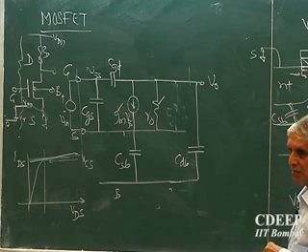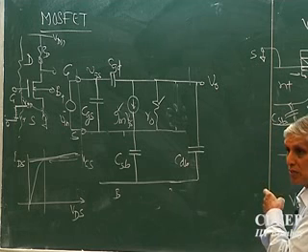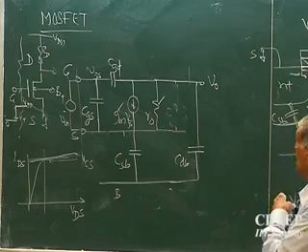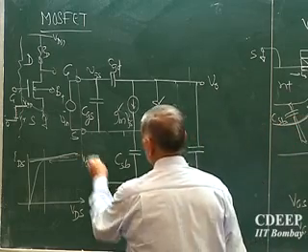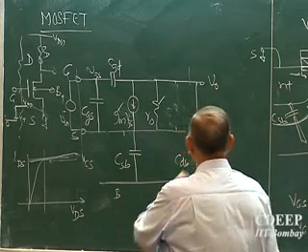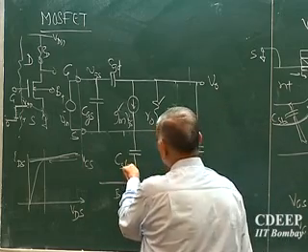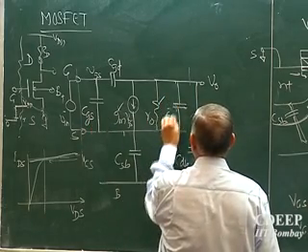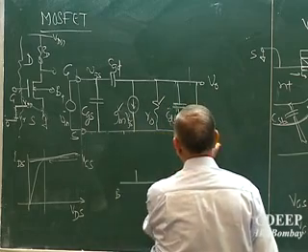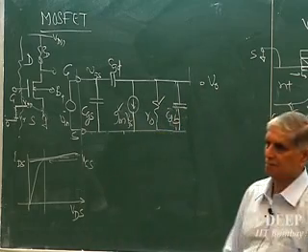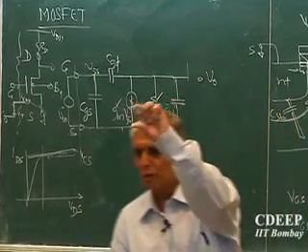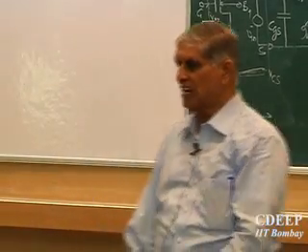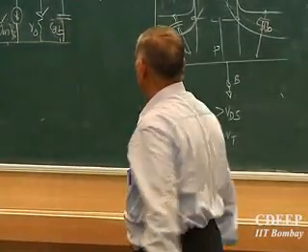Is that clear? So in real life, this will be the equivalent circuit of a MOS transistor. For simplicity, we say that source and bulk are at the same potential. So we neglect CSB in many cases. We only use CGS and you put an equivalent capacitor CDB here and remove this part from here. Is that clear? If the bulk and the source have the same potential, we say okay, it is CDB, same as CDS, and therefore you put the capacitance here.